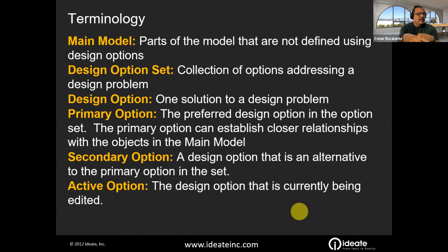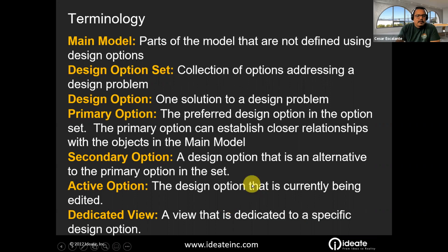You can deactivate the options and go back to the main model, but design options need to be edited as a separate layout in a view. And then for every design option, we create dedicated views. So just like we created dedicated views for different phases, we also create dedicated views for design options.